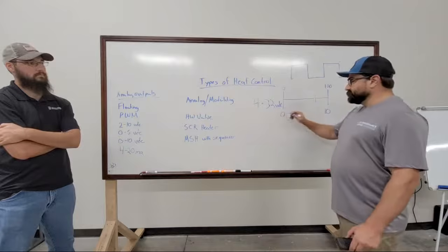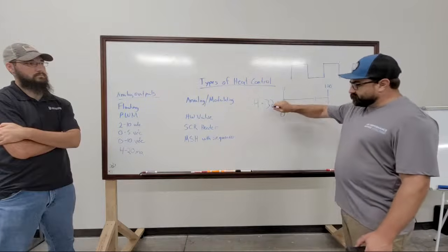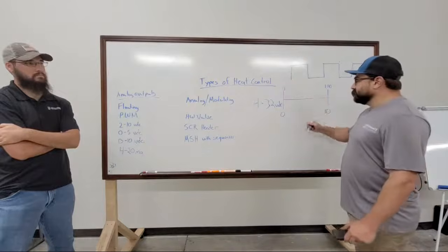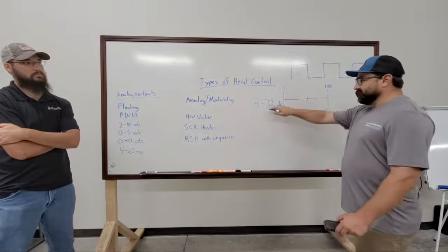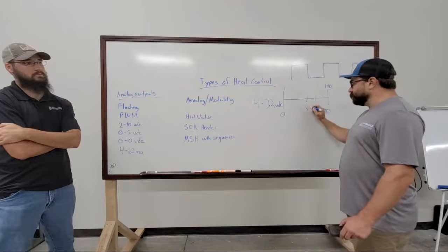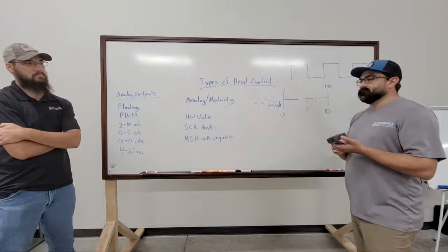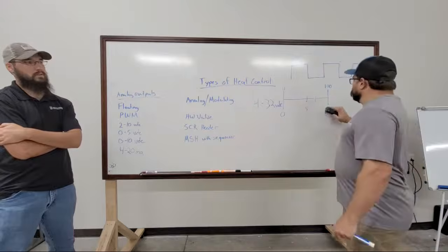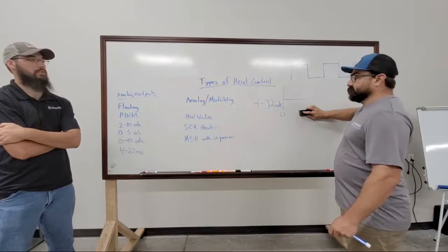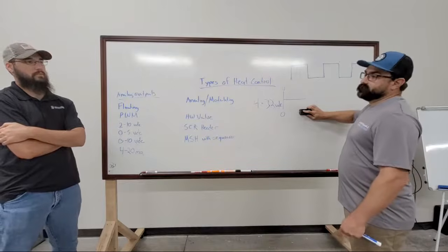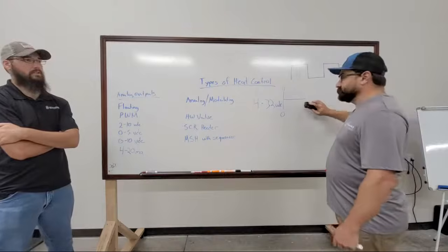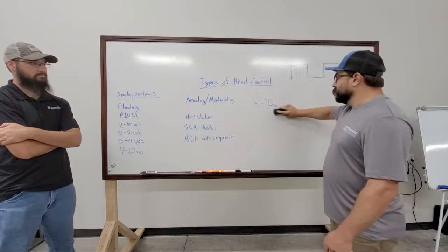And then what it wanted was that voltage over tenths of a second, just like this scale. So for 50%, I would give it anything from 4 to 32 volts for 5/10 of a second, and it would run up to 50%. And it didn't matter if it was 20 volts or 10 volts. It could be 31 volts, or it could be 4.5 volts, or it could be 15 volts, or it could be 11. It just didn't care. They're just looking at the modulated signal. It just wanted that pulse.